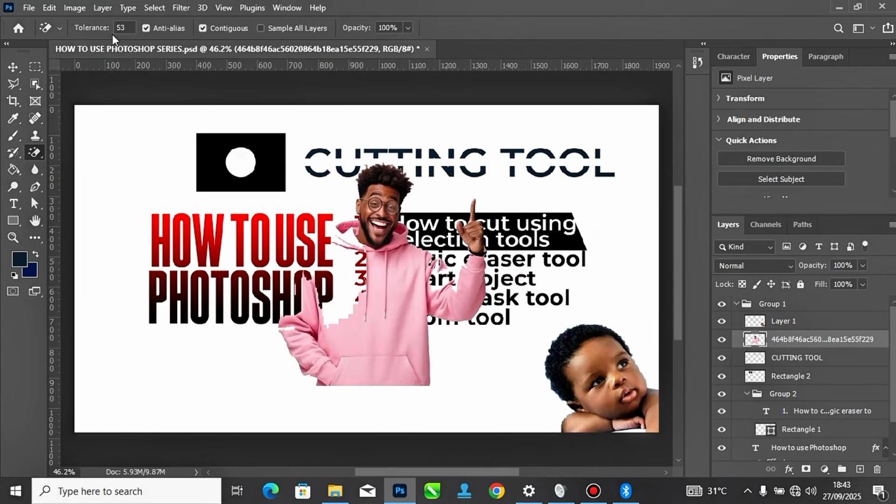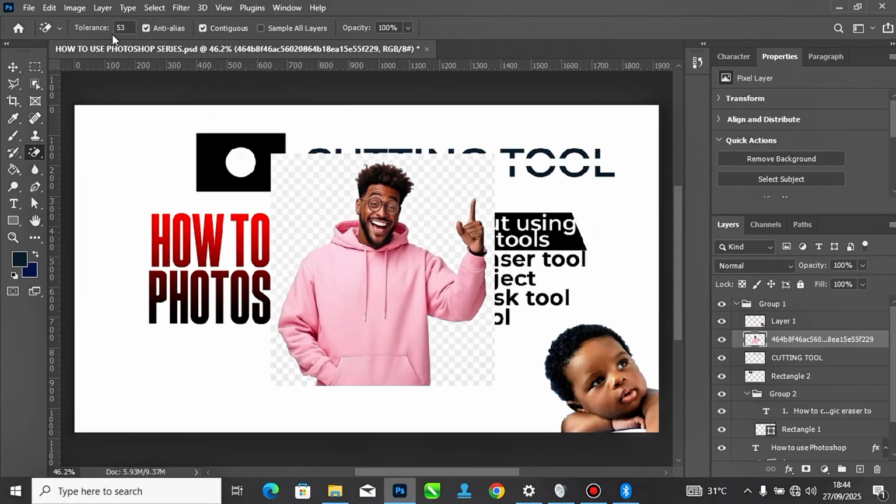There is a slight difference. There is a slight similarity between the image, the cloth, and the white background. So there is a kind of white feel on the cloth. So I'm going to reduce the tolerance so that it reduces the detection of the white, so I do not detect the white that is on the cloth. Then I'll click again. I reduce it to 16.